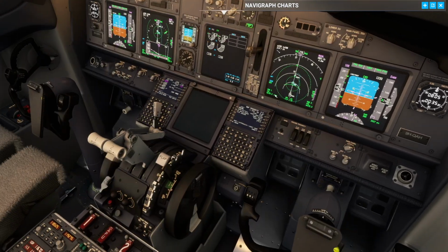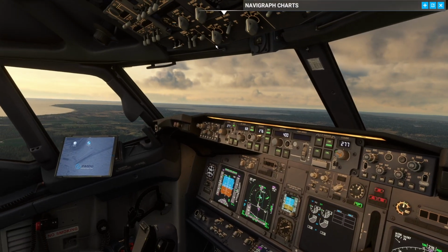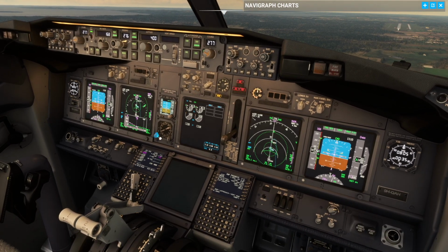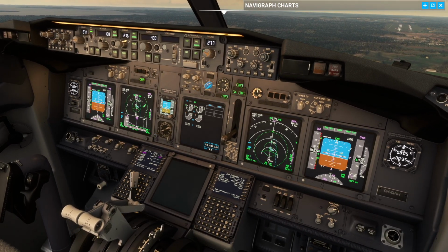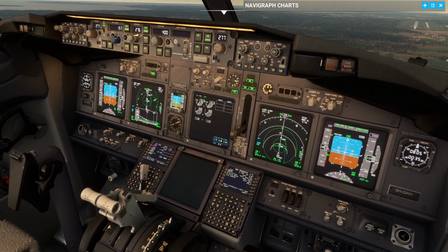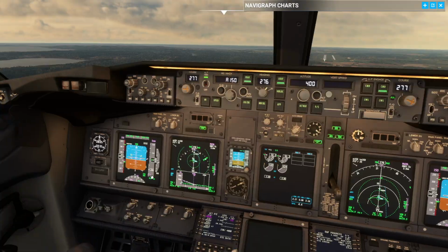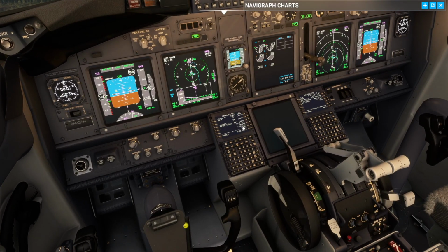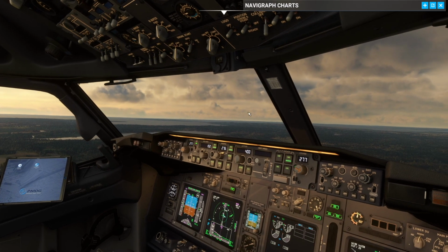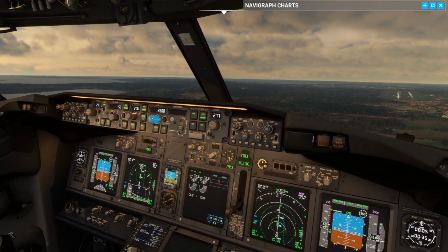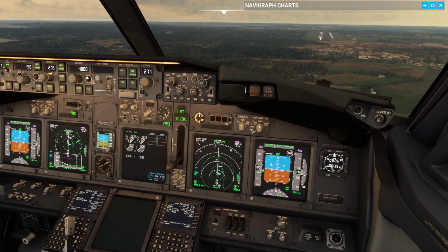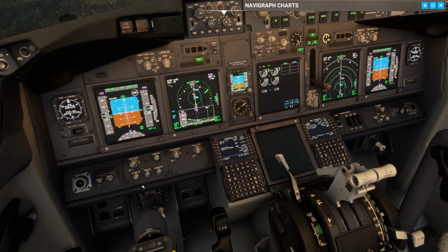Okay, configure a little bit early, gear down, flap 15, landing checklist. Flap start switch is continuous, recall check, speed brakes is arm green light, landing gear down, three green, auto brake 3 set, flaps 30 please. Flaps 30, 30 green light, landing lights on, clear to land, and reset the missed approach altitude at 1,000 here. We heard the call, 1,000 feet, missed approach altitude 4,000 feet is set.